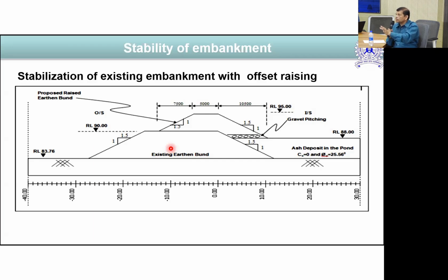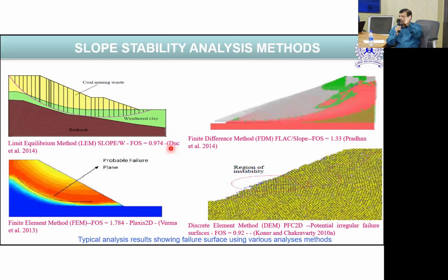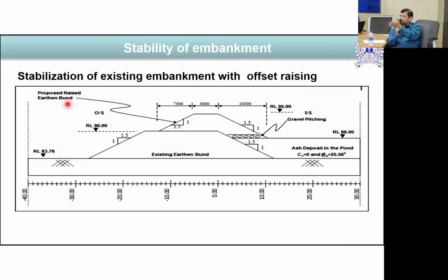If you think it's not okay, then you change your search method to find the one which you think is okay. Because for any slip circle very close to the face, there will be some generated very close to the face that can fail, and that will give you the minimum, but that is a local failure.